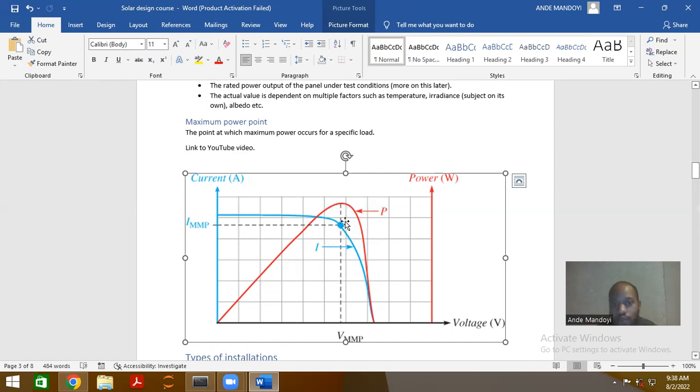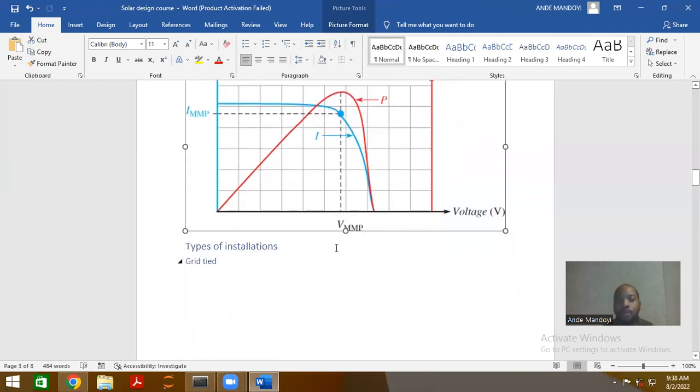It does adjust the voltage such that you get your maximum power point at any load. So if you're pulling this much current, it'll adjust the voltage such that you are at this optimal power point. Hope that makes sense.